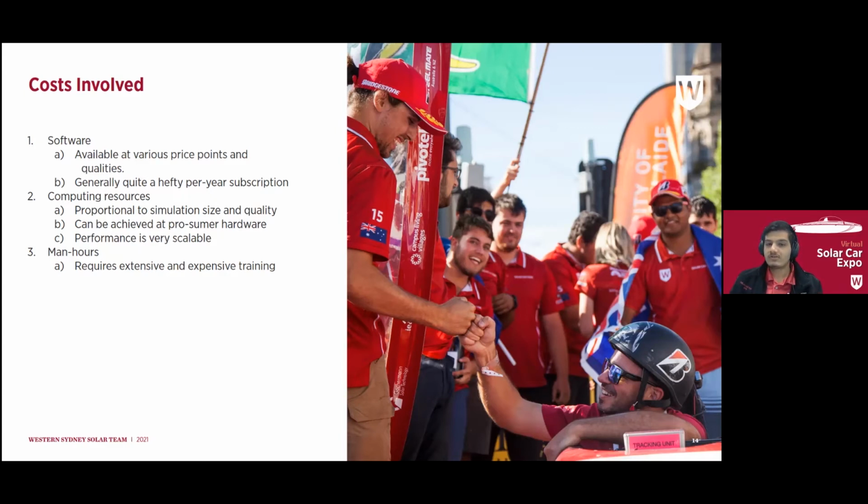Computing resources are also very important. These simulations are very, very computationally intensive, especially CFD, where the mesh sizes are quite a bit larger. As an example, we were able to run the level of CFD simulation that got to within that 1% of real world for the Solar Car air body, a sim that had approximately 50 million cells, in less than 48 hours on a prosumer workstation that was in the ballpark of $4,000.